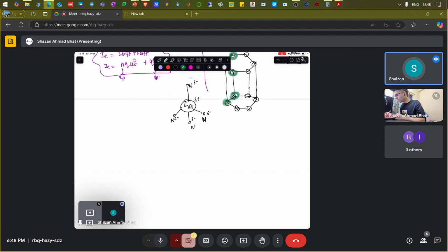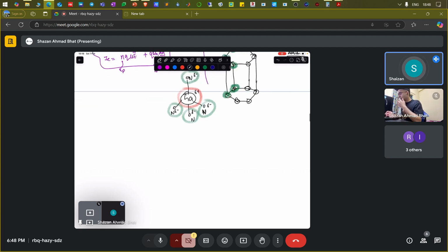Okay, that means the electron cloud is mostly towards the nitrogen, and slightly there is positive charge over the gallium. Because of that, you know that it will set up an electric field. So now when you consider all of the components of these particular charges, you see that the direction of the electric field is from positive to negative, from gallium to nitrogen.